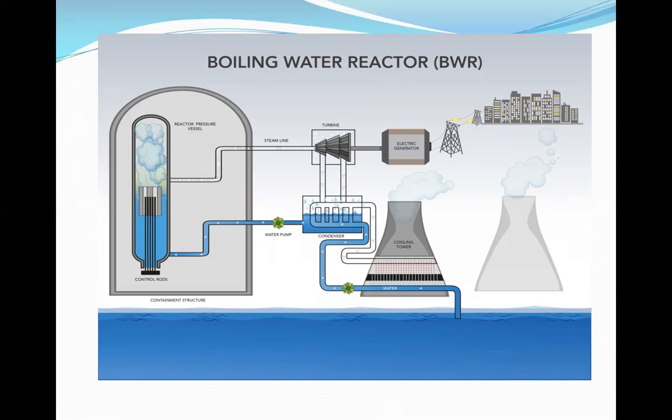Here, the main advantage of this BWR is that the heat exchanger circuit is eliminated, and consequently, there is a gain in thermal efficiency. By avoiding this extra circuit, we can increase the thermal efficiency, and also we can gain in cost.